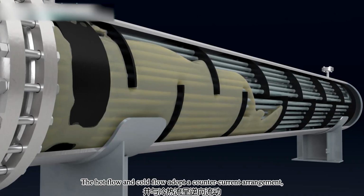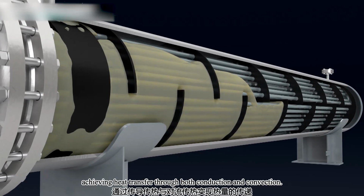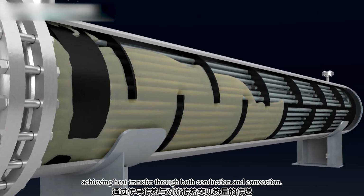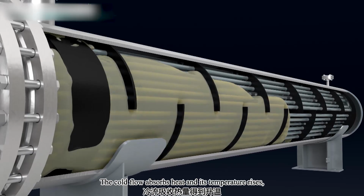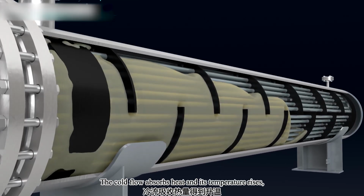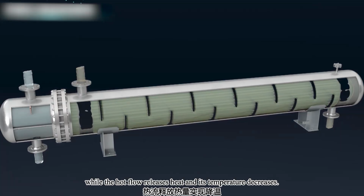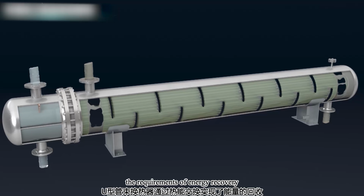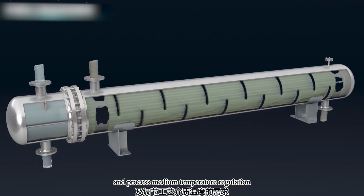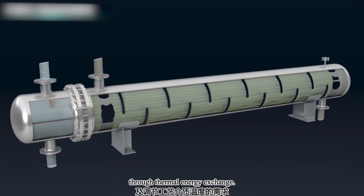The hot flow and cold flow adopt a counter-current arrangement, achieving heat transfer through both conduction and convection. The cold flow absorbs heat and its temperature rises, while the hot flow releases heat and its temperature decreases. The U-tube bundle heat exchanger fulfills the requirements of energy recovery and process medium temperature regulation through thermal energy exchange.